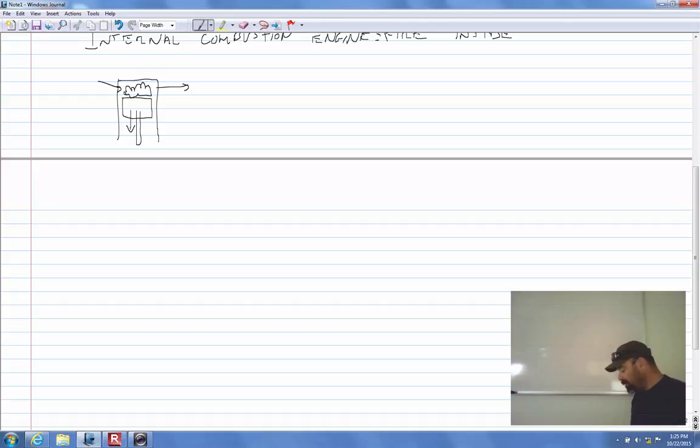So does the oil burn during that explosion? A little bit, not really. I mean, you'll get a pretty good smoke cloud out of it. We know how gasoline burns compared to diesel fuel burns. It takes longer. The heavier that oil is, the longer it takes to burn. Well, if you've got this engine turning 18,000 RPMs, how long is that oil in that cylinder under that direct flame? Not very long. So typically, it's very, very dirty, and you get a lot of oil coming out of the exhaust. It's not a very efficient burn.